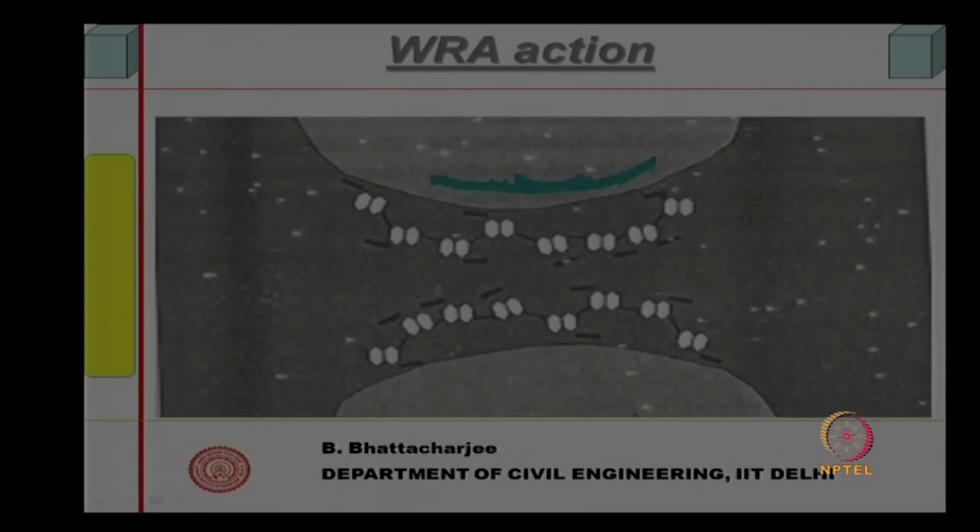Since SNFs are linear chain polymers, they are creating negative charges, and these negative charges repel each other. This is another particle. This is showing SNF. You can see the naphthalene rings, naphthalene double rings. So, this is actually SNF action shown.